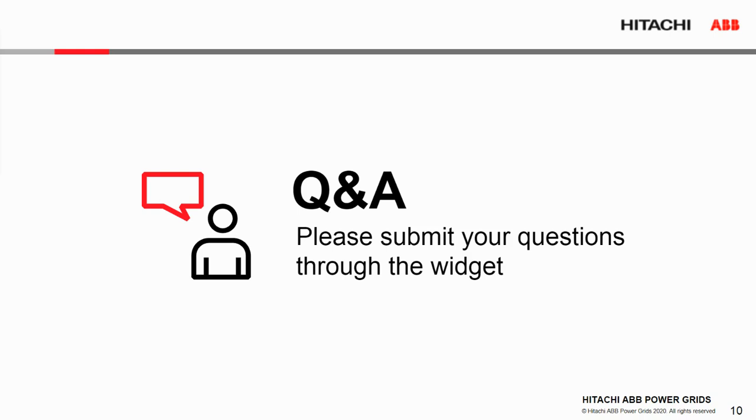One question: can you cover 9 bay CT with 1 REB 670? If more than 1 is required and moving to 3 is the only option, or can it be covered by 2? Well, this is talking specifically about ABB's capability. So the answer is the maximum you can cover with 1 relay is 8. More than that, unfortunately, you would need 3 boxes. With 3 boxes you can cover 24 single phase.